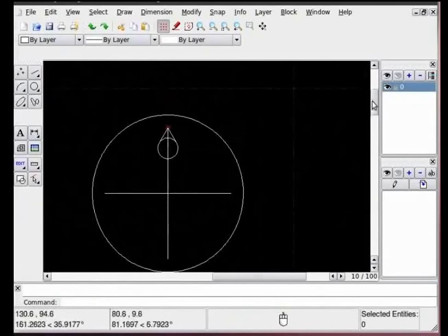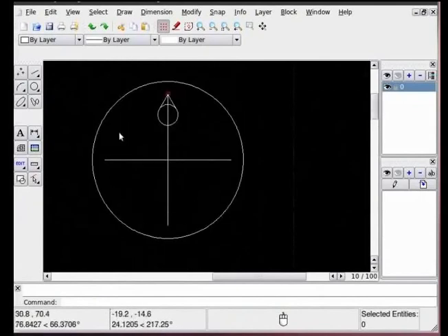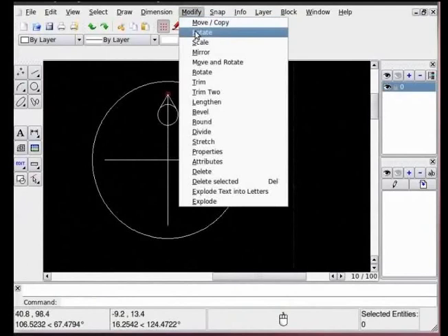Let's say I want to create 4 copies of this object inside this circle. For this, we will use rotate to tool or counter rotate. Let's select this tool by going to modify. Here, this first rotate tool can create single or multiple rotated copies of an object. Right below there is move and rotate, which will let you rotate objects with specified distance and create multiple copies. But we will choose this rotate tool, which will let me create multiple copies of objects going in circular direction around a point. So select that.